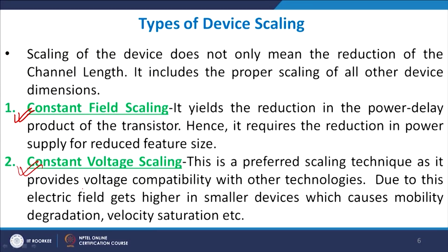What is constant voltage scaling? Well, this is a preferred scaling technique as it provides voltage compatibility with other technologies. The cost you pay for it is that, whereas in the first case when you lower your channel length you also lower your VDD, in this case you do not do that, you keep your voltage constant. When you keep your voltage constant, then electric field enhancement is there, mobility reduction is there, and so on and so forth. But then it is compatible with technology.